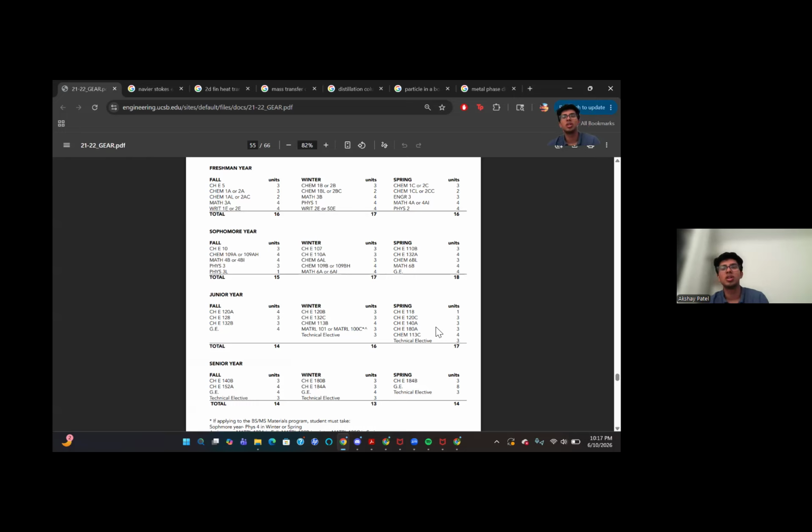You have a distillation column, like the batch distillation column that we had at the bottom. We had a batch of solution, and we just had trays in the middle, and we had to model how things would separate out. We actually measured it and saw if our model predicted what actually happened, and we analyzed what went wrong if it didn't happen that way, and stuff like that.